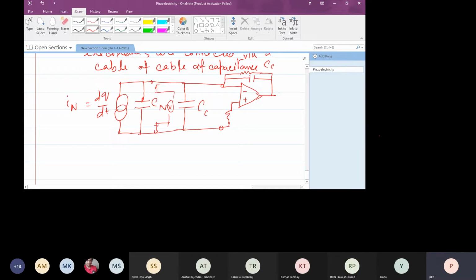So this is the feedback capacitance, you can say. This is a very high value, maybe greater than 10 megohm or so. Then of course the op-amp can drive the meter, a digital meter, whatever the load here, which could be the input impedance of the voltmeter, 1 megohm for practical. This is the RL, so voltage V.